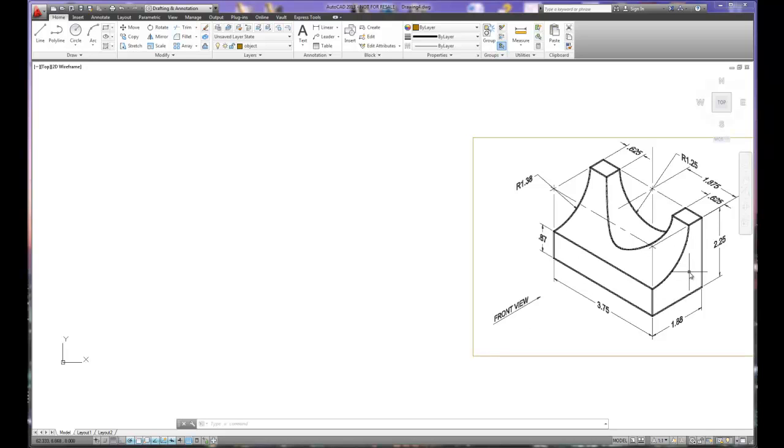Because when we're creating this as a 3D solid, what I would like to do is take the side view shape and extrude it the distance of 3.75. And again, extrusion is just taking a shape and expanding it to a specific distance. We'll show you some of the other really cool features of this solids modeling software after we're done building this.